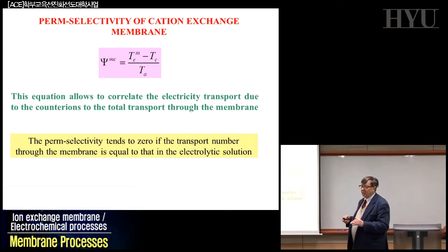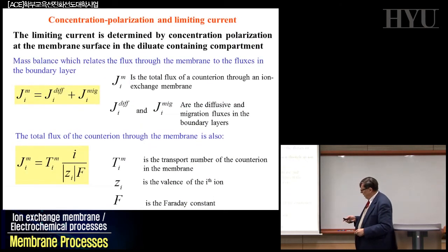In anionic membranes, we still have this kind of phenomenon, for which you decrease the charge density in the membrane because some of the chemicals present in the solution interact with the fixed charge and neutralize it, so decreasing charge density, and that means decreasing the permselectivity. So we always have to take care of this, and that is not easy to predict. It depends on what is in the solution. If there is something unexpected in the solution that you have not been able to separate before, this is big fouling on the ion exchange system that you have to take care of.